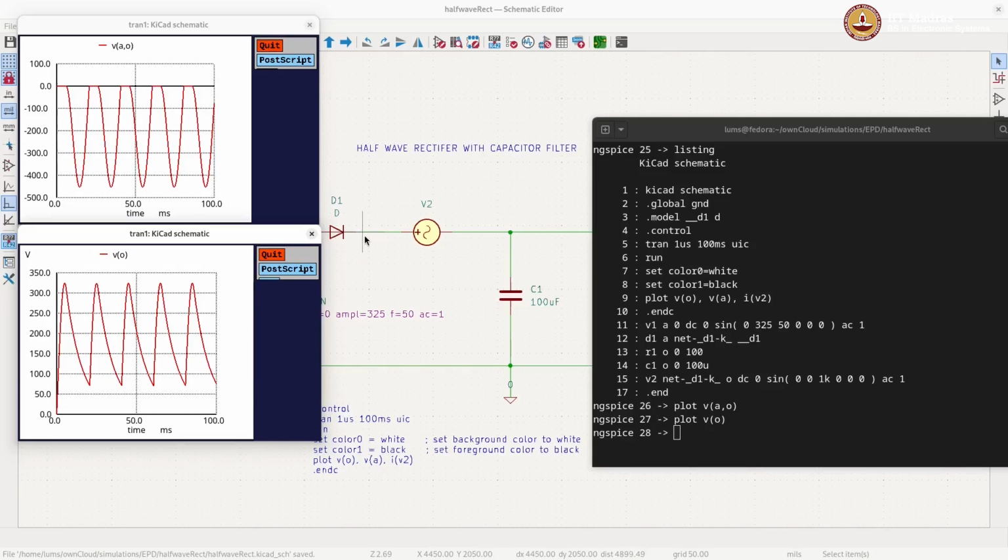diode rating. So we normally design that, okay, if the ripple is small, then this will be at 325 and the minus 325, so 650. We say 650 should be the rating of the diode. That's how we went by theory. But if the ripple is large, then you can even bring down the rating of the diode because the max value is still lesser. So these are things that you can actually play around with and really get a feel for it.